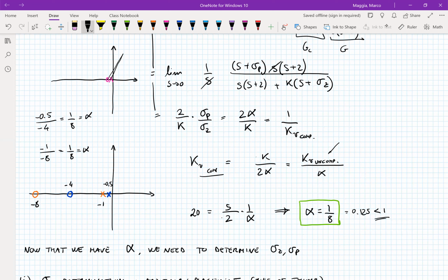You can think about this in terms of when you have a small angle associated with a compensator, you're not going to modify the root locus much. The larger the angle associated with the compensator, the more the uncompensated root locus will bend. The objective for a lag compensator is not to modify the root locus, it's just to modify the steady state error. So we don't want the pole and the zero to be far apart. And therefore, we must choose both of them to be quite close to the imaginary axis.